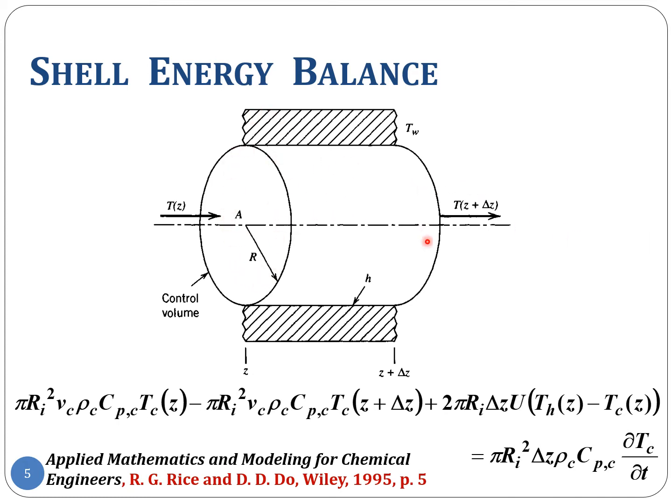And therefore such a set of cross sections going from z to z plus delta z is given by 2 pi r, which is basically the circumference, times the thickness, which is delta z, and through each such cross section you would have this heat transferred, and that is why this energy is added into the bulk fluid itself, right?